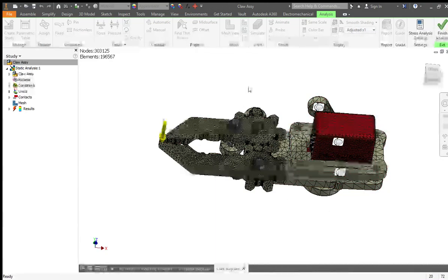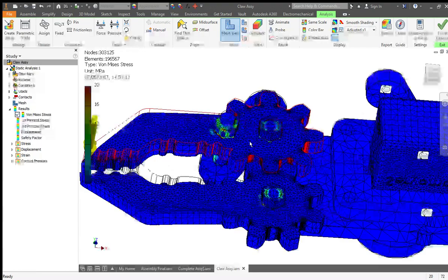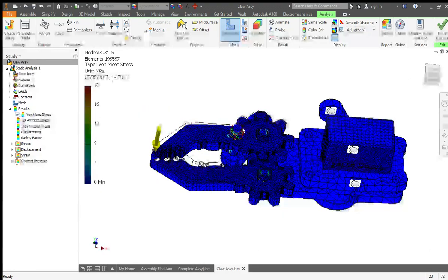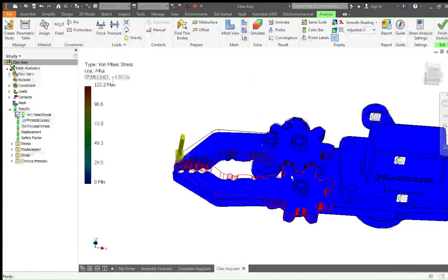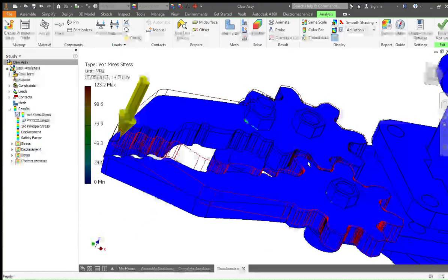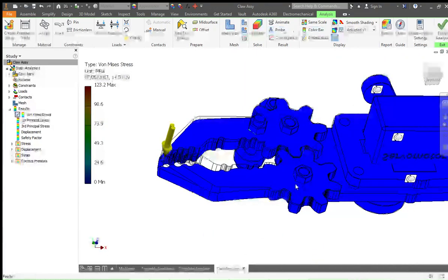This is what that looks like when you've just finished your stress analysis. So you can see there's a few occurrences of stress on the bottom of these bolts, but not much else. But you can actually fine tune that with the color bar. So make that red area, rather than the maximum stress experienced, something like 50 for now. So just half that result, and you can see that gives you a bit higher definition of where that stress is being experienced. And I'm going to take that right down to 20, just so we can get a clear view. And you can see that most of that stress is being experienced in this bolt here, and the surrounding bolts as part of the claw.